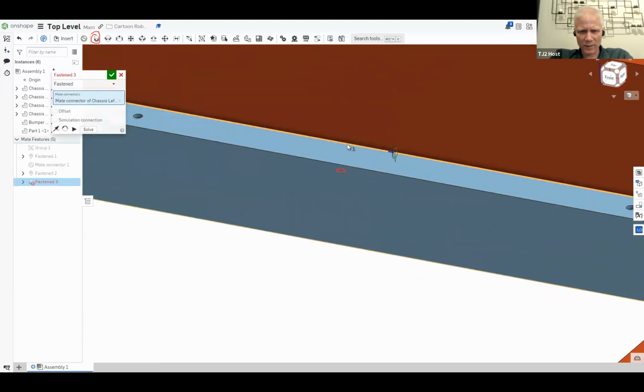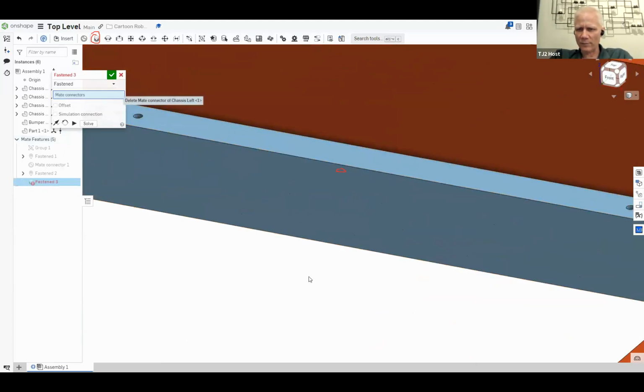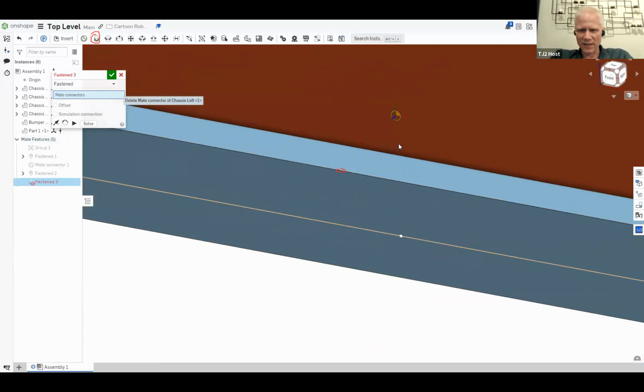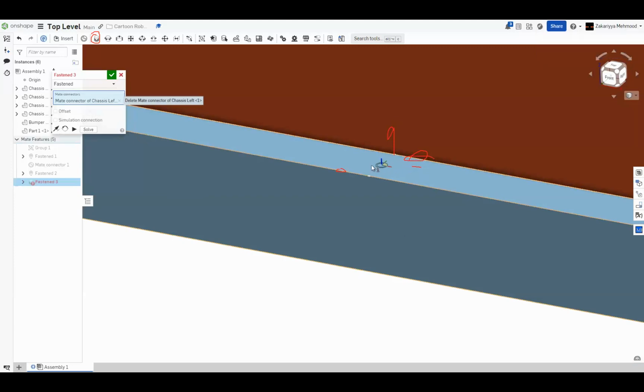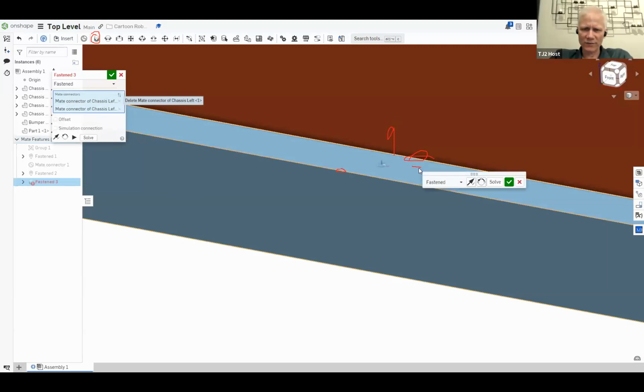You have to be careful when you're selecting these things. You have to pay attention. You want to pick this edge, and you want the middle of that edge. We want to find one where the Z is pointing straight up this way, so you have to approach it from different areas. Like maybe try touching this surface. There. Can you see? Move it over, move to the back. If you hold Shift while you're on that surface, you can select that point. In that orientation, then hold Shift and then hold that button.